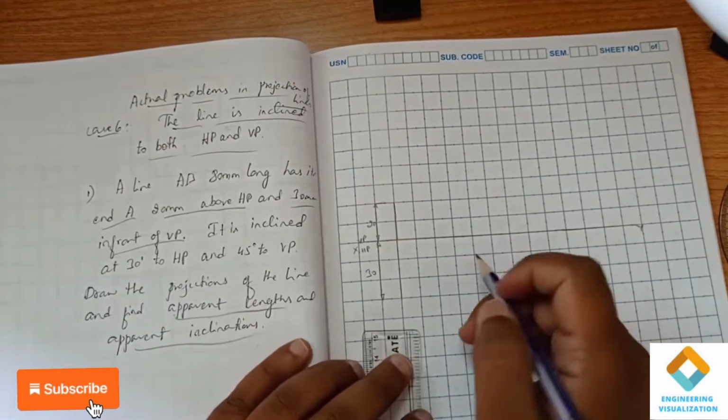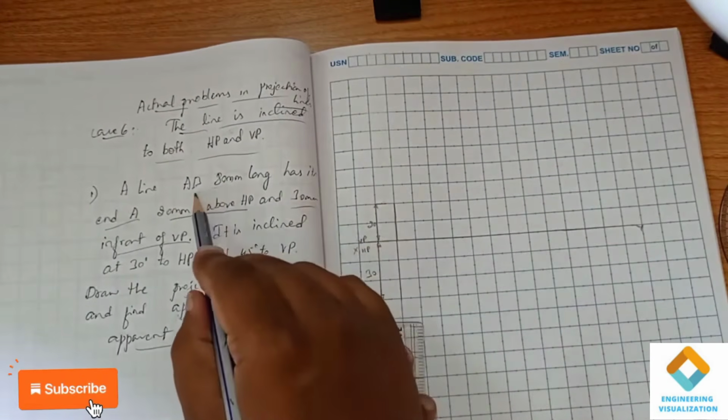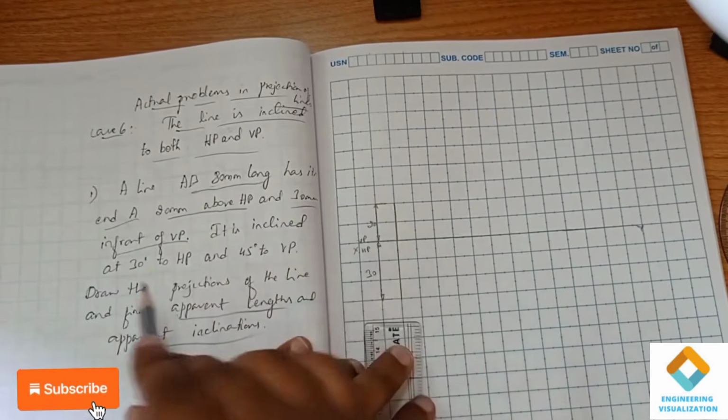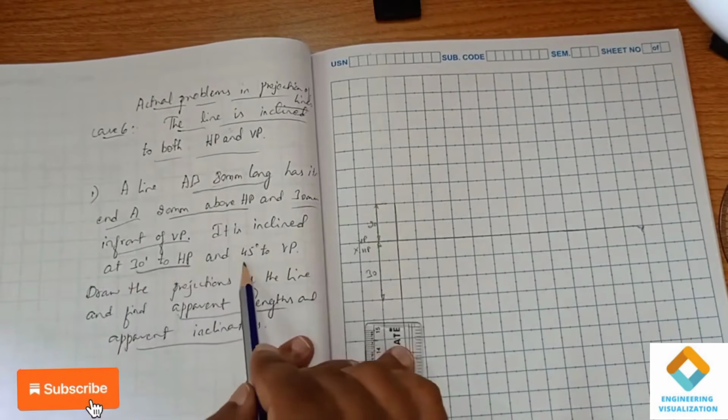Here the length of the line is 80 mm. So AB is nothing but the true length. You have to find out the apparent length. The angles of inclination given are 30 degrees to HP and 45 degrees to VP.